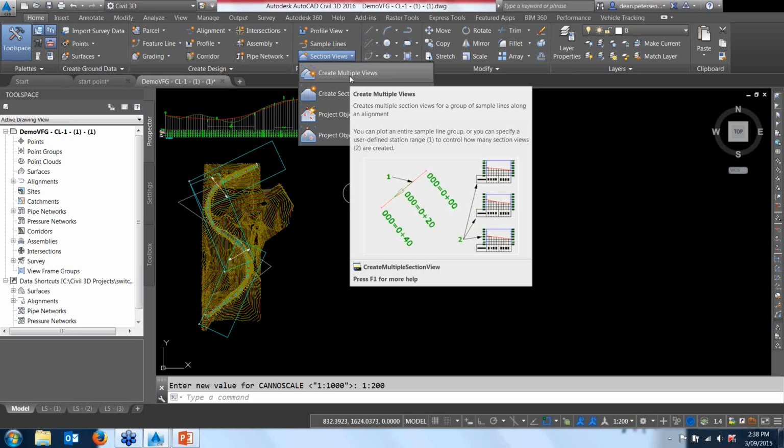There's no button that says don't update my cross sections. And for that reason, when it does a regen, it has to reproduce all of them one after the other, and there are a few. So that is why either do them in a separate drawing like this, or you can do them in your design drawing, but do it at the end of the design process, so it's not slowing you down while you're waiting for things to regen while you're doing your design.